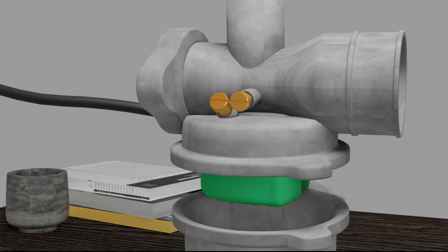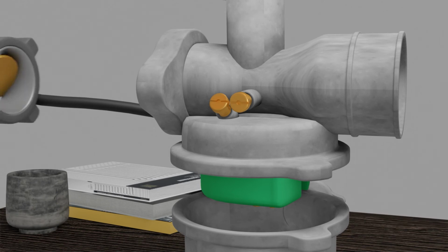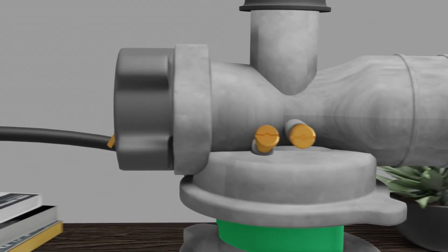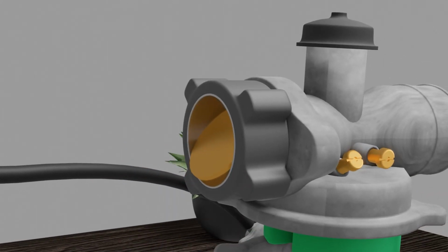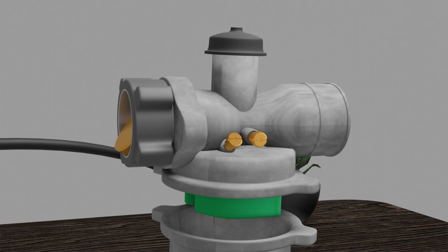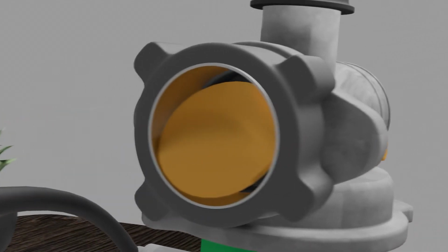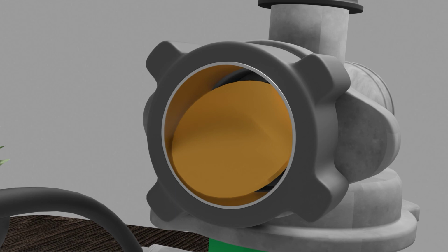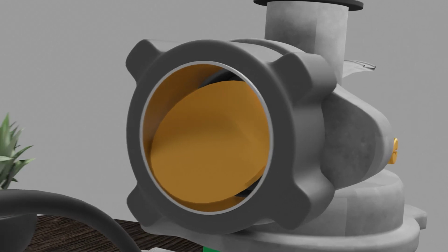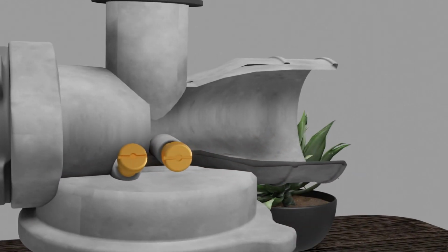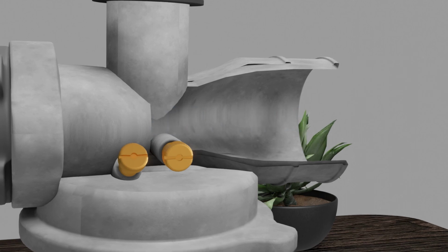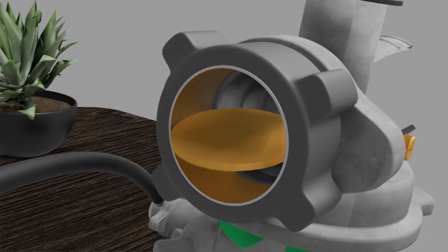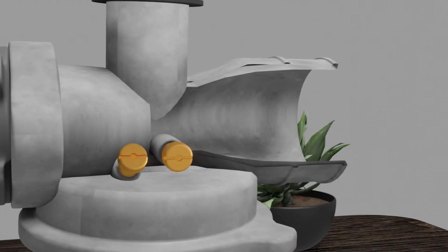Besides using a piston, some carburetors use a throttle valve that is located after the carburetor. It is almost the same as the piston. If the throttle position is vertical, it will resist the airflow, so the airflow in the carburetor is lower. It makes a low difference of pressure, which leads to lower fuel supply. But when the throttle position is more horizontal, it loses the resistance, so the airflow through the carburetor will be faster and the difference of pressure is also bigger.